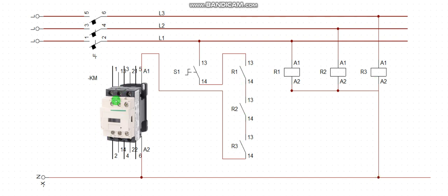So you want to supply a contactor, you want to feed a contactor. You all know that a contactor requires a voltage monitor for phase failure. The phase must be complete for the contactor for the motor to operate. Okay, so an induction motor requires direct three-phase supply if you are using a three-phase motor. So in the isolation of one phase, the contactor shouldn't close, so that the motor will not burn out. It must be three phases. If one phase fails, the contactor shouldn't energize. The power shouldn't go to the induction motor.